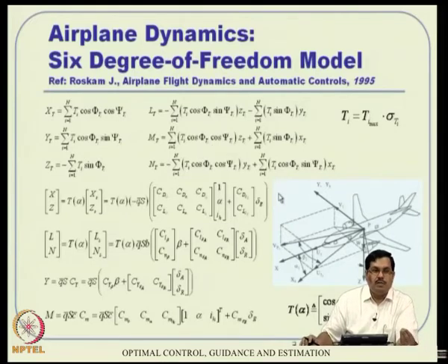If thrust has a small component, let us say some sine of 2 degree or 3 degree, but thrust is a large quantity. So, that quantity multiplied by sine 5 degree also becomes a big quantity, which will aid the lift actually in a way. So, like that there are various ways.